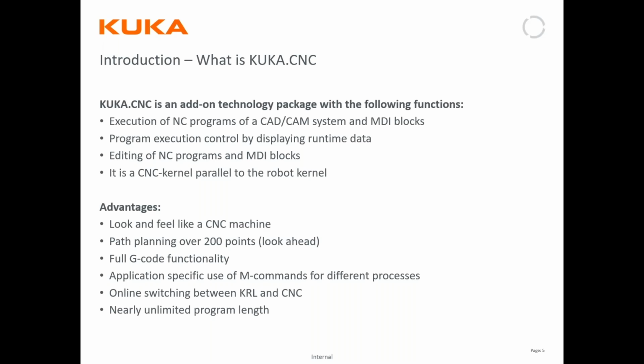Application-specific M commands can also be customized for different machining and automation processes. Seamless switching between KRL and CNC, with which users can switch between KUKA robot language and CNC mode easily. Nearly unlimited or with no restrictions on the program size, allowing for complex machining tasks.